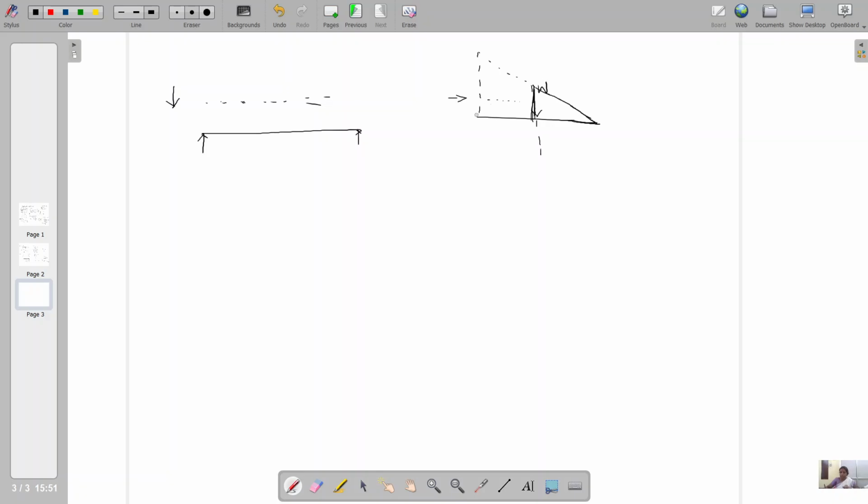But at the same time, when the load passes from the point A, the negative shear force will be increased. The negative ordinate will be increased to some extent and it will have some magnitude when the load is located at the section, because it should be in equilibrium.